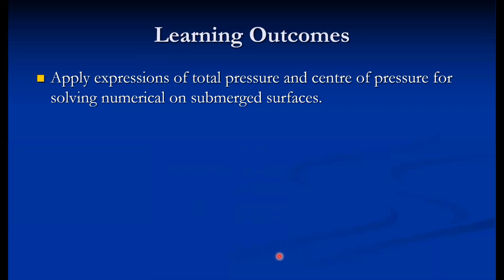As far as the horizontal plane surface is concerned, there is no such numerical because there are no complications there. The depth of water directly gives us x bar, and h bar is equal to x bar. So there are no complications in horizontal plane surfaces. Thank you very much.